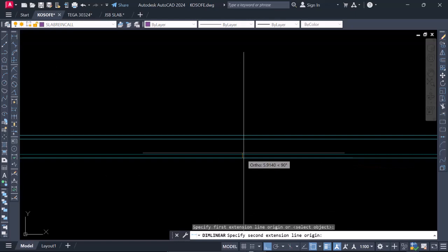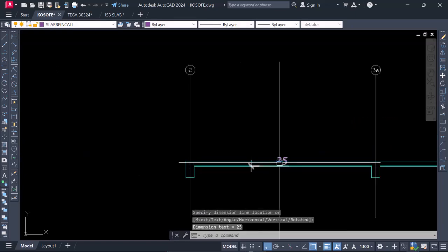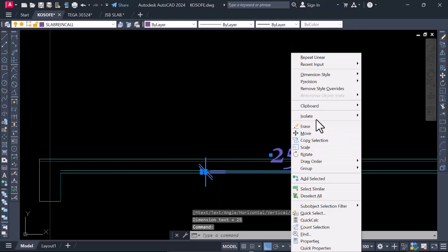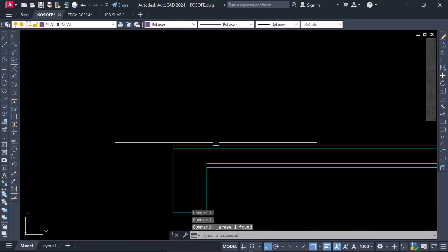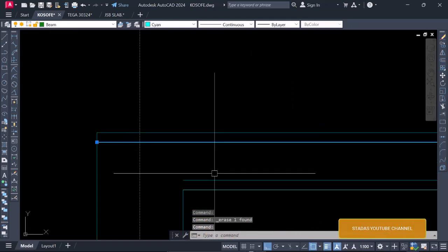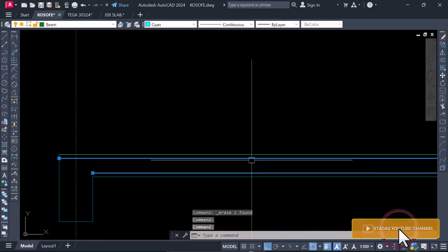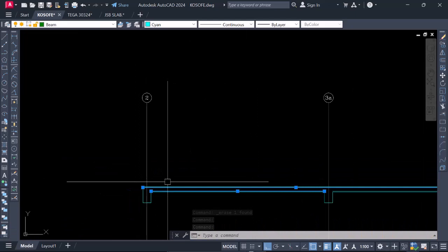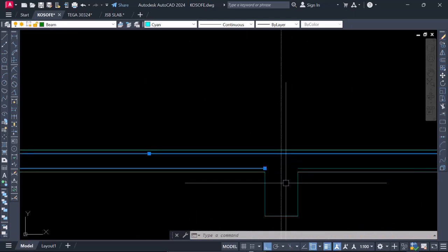We're going to have 25 to be our concrete cover, all right? Both top and bottom, because that's what we're going to do. So all our reinforcement is going to be set along these two boundaries. It's not going to exceed over this boundary, okay? So right away, we can start our bottom reinforcement.